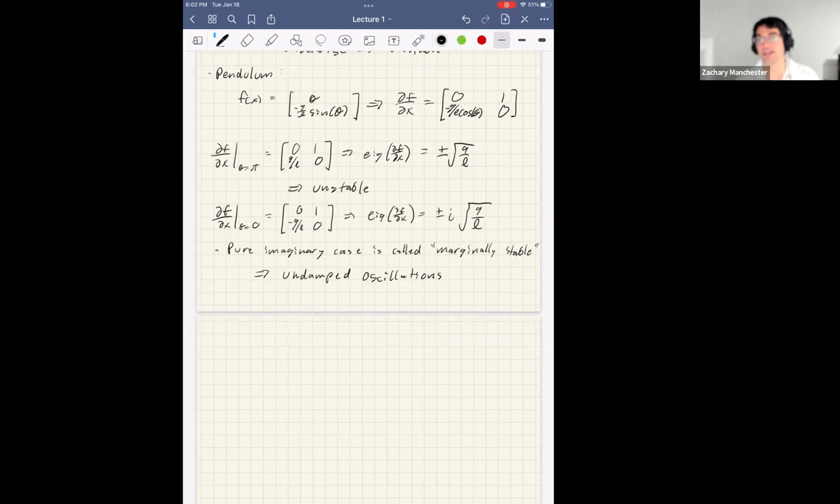It turns out for the pendulum here, which is a nonlinear system, it really is this pure oscillatory motion thing, but in general, if you have a nonlinear system and this happens, you can't trust the result, and you basically want to be very careful and or assume it's unstable. As just a last comment on this, if we add damping to the system, which we can definitely do with our control input, right?